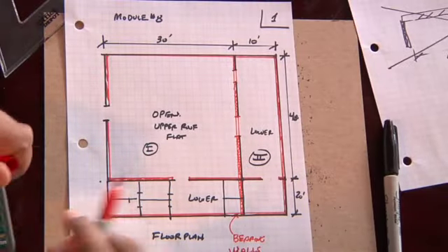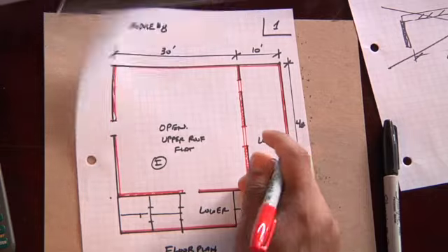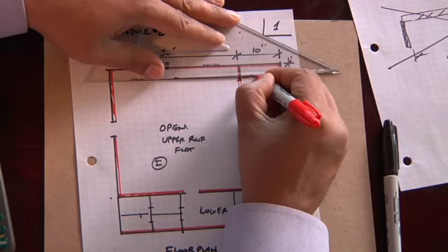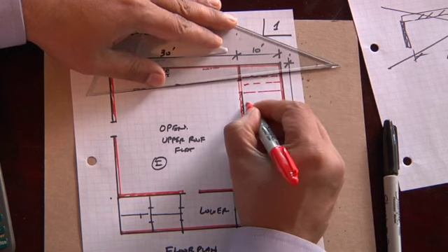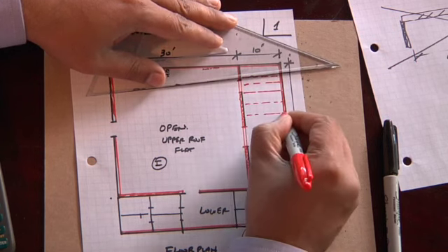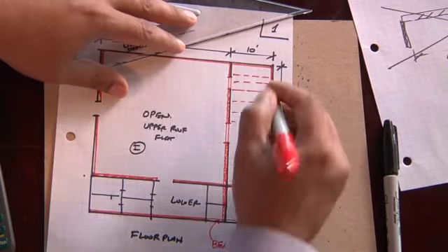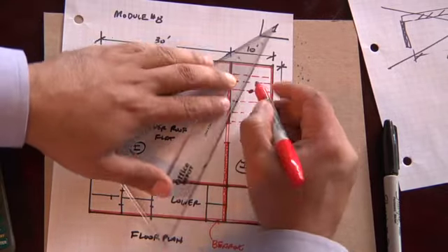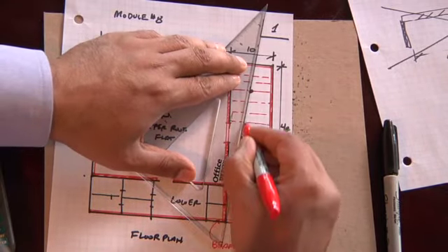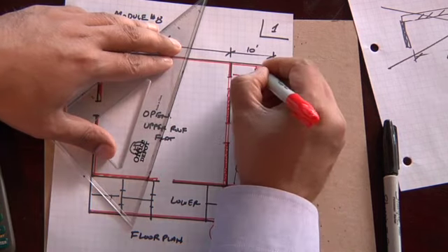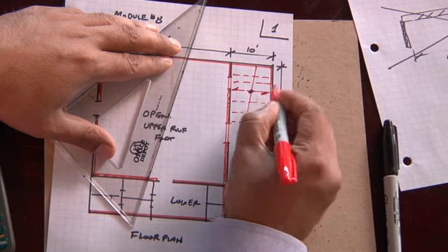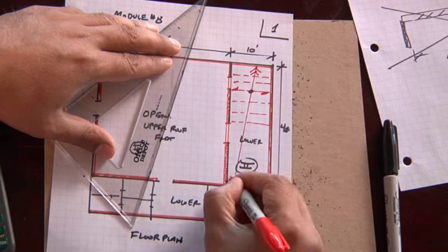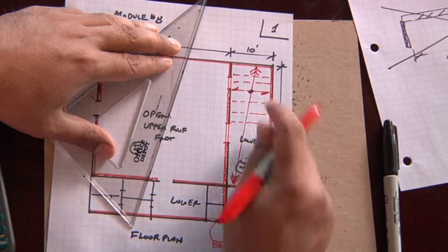So on your floor plan layout, on this portion of the roof, we're going to go with a joist layout, which is going to follow really what I think is common sense. And I won't draw them all out, but I'll just use some notation here to indicate. This is an old style notation, some of you may remember this, which indicates the direction of the rafters and the spacing.